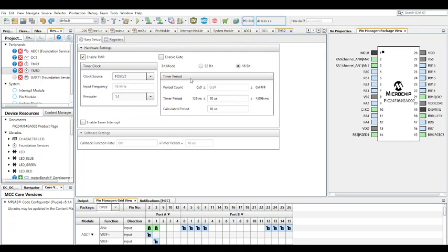And if we look at timer 2 there, the switching frequency in this example is 100 kilohertz, and I find the 100 kilohertz to be a really nice frequency to use, because it's a nice balance between the speed. So your settling time will be better because now you can make your control loop sampling frequency faster.